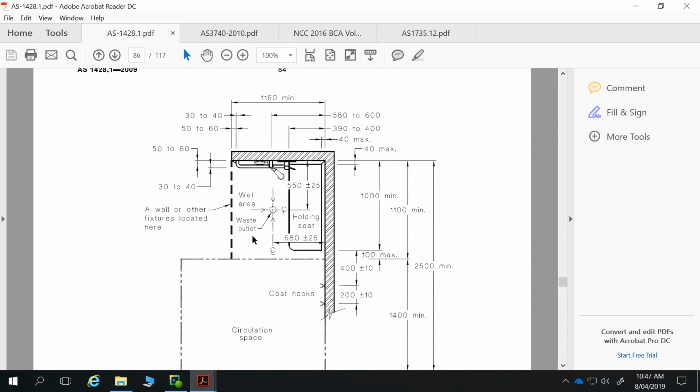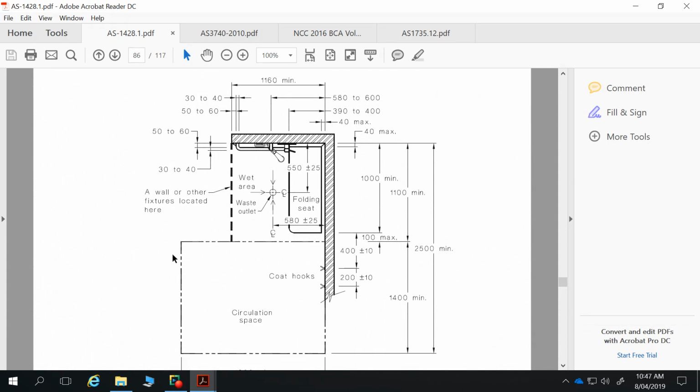the short of it is that with a disabled bathroom, you're not allowed to have any defined set downs or hobs to enclose that shower area. That shower area has to be part of the open floor. So just like when we looked at our changes in ground levels, etc., for finished floors like carpets, etc., or for paving, same requirements are applying to our bathroom and our shower area. We can't have any steps greater than 3 millimeters in that. So that means we have to have an unenclosed shower.